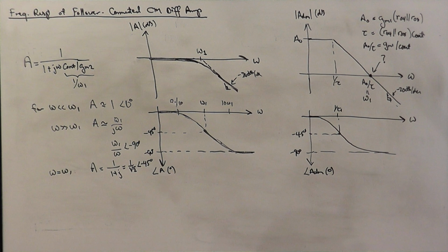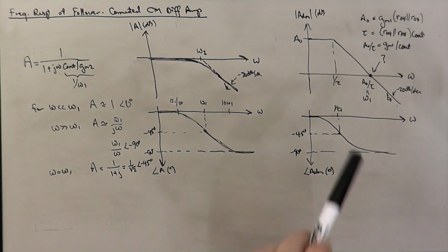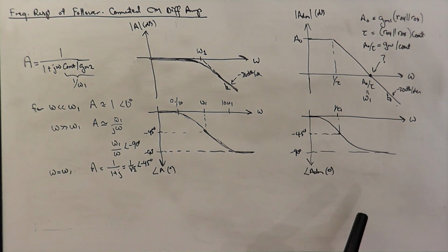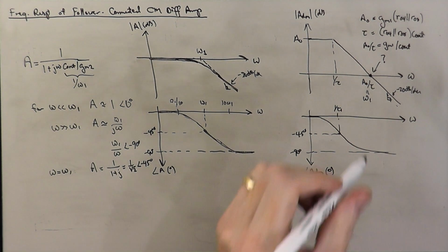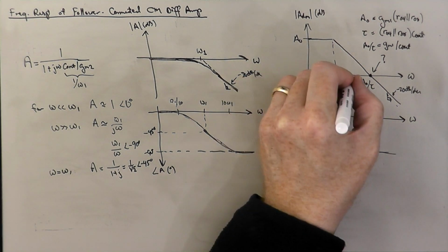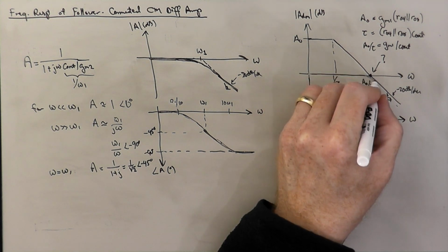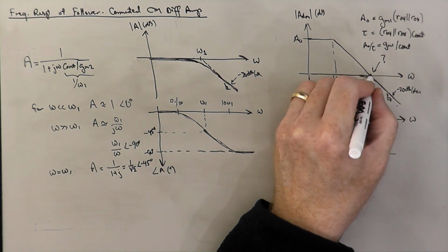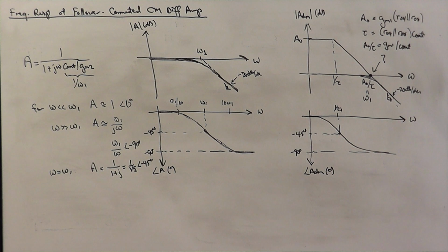So when we take our amplifier that has the open loop gain shown in this Bode plot and configure it as a unity gain follower, what we find is that we basically get the corner frequency corresponding to the place where the open loop gain crosses over the 0 dB line. So the unity gain crossover frequency is what that's typically called in the open loop response. And that's typically denoted by omega 1. Okay, so just wanted to go through that.